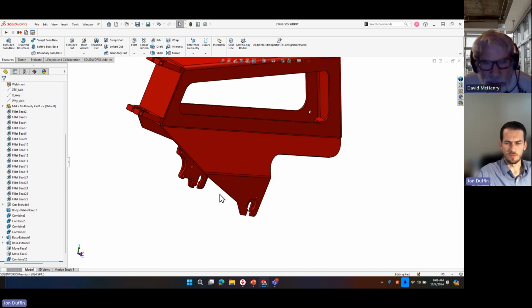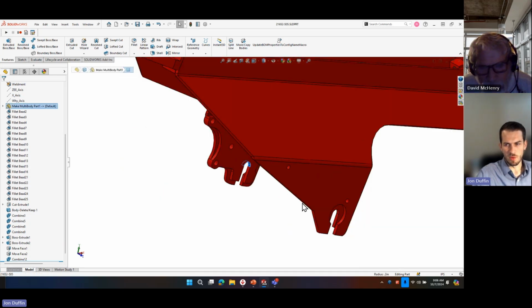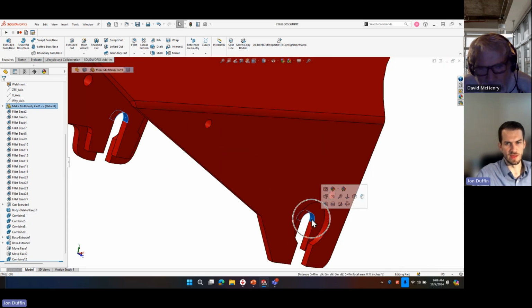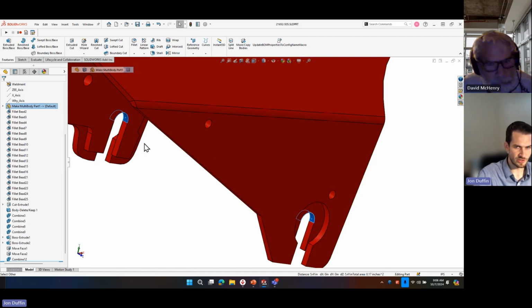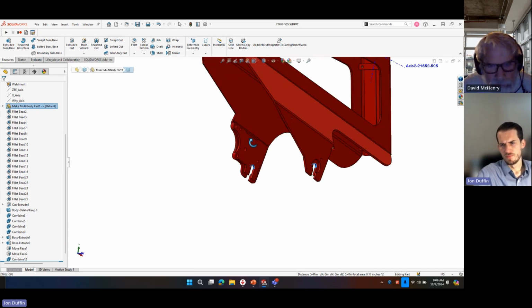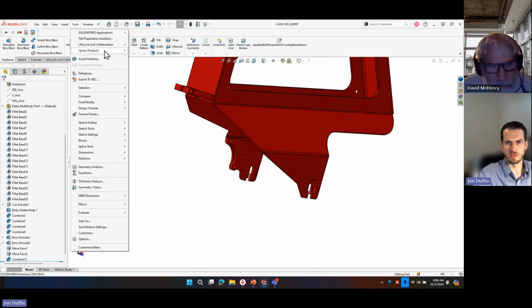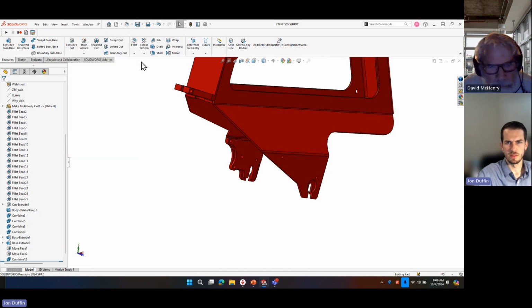Yeah, no, I'd say that's fair. When we say these are fixed, whenever you're assuming something's fixed, you're assuming it's infinitely rigid, it can't move at all. We're assuming whatever axle is on there, we get no movement left or right either, which we don't expect the loading to do, but you do fix it in that way as well. So there are multiple ways to go about this, but you're absolutely right from a Sim Express standpoint.